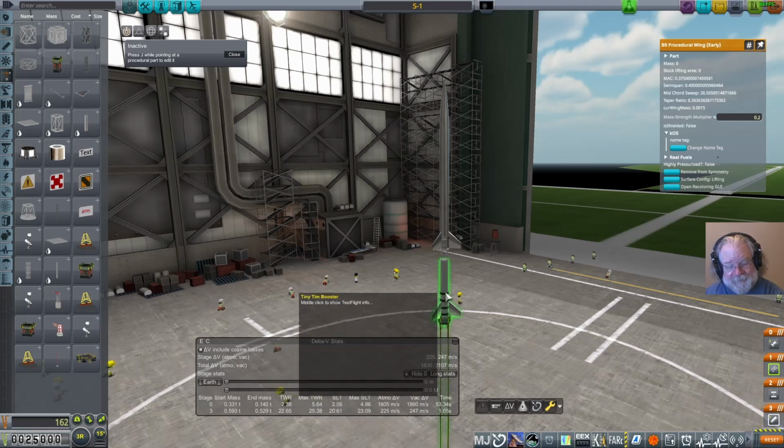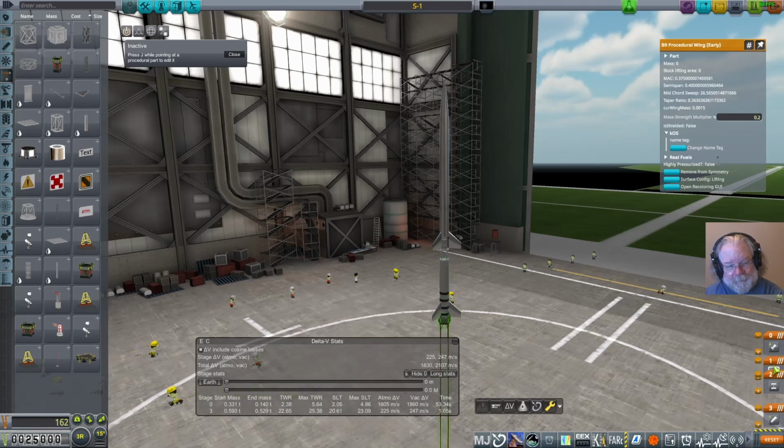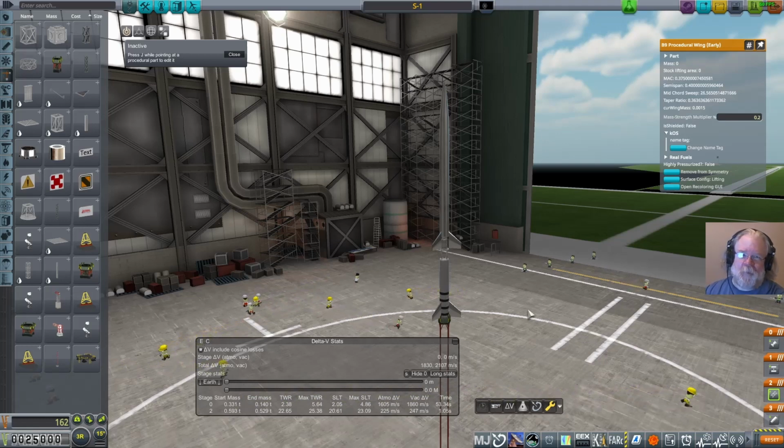What I want to do is ignite my booster, and then I'm going to release the launch clamp when the booster has developed enough thrust to get us off the launch pad. Now, for this guy, it's immediate, but I want to use this logic in general. This way, if the engine doesn't start, we never release the launch clamp, and everything is still there on the launch pad. We can roll it back in and figure out what's wrong with it. If it ignites and doesn't produce enough thrust, we hold it in place, because if we release the launch clamp, we don't have enough thrust to get it into the sky. We just kind of fall over and things destroy themselves. So keep the launch clamp until we have more thrust than weight.